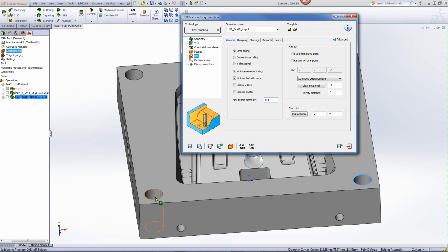So this value is not allowing the tool to go all the way in. But you remember that it actually spotted a little on the bottom. That's because the bottom of the tool is 8 millimeters in diameter. So if I add 8 to 8.8, we have 16.8, allowing for a little bit of the bottom of the tool to actually machine a little bit of this.